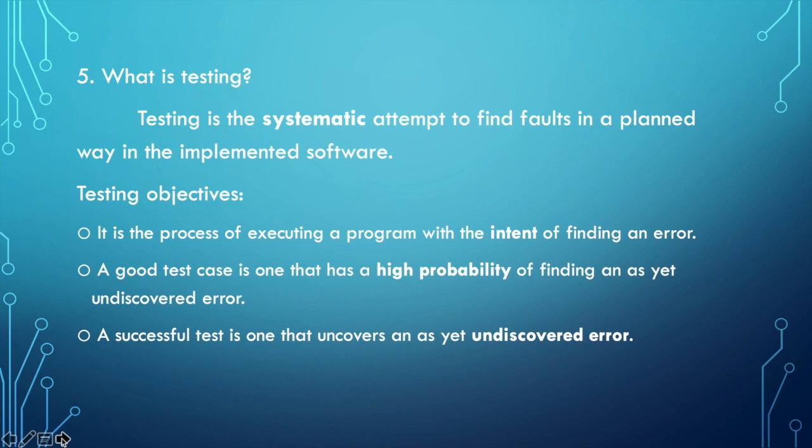And probably in that MCAS, the undiscovered error was that they rely on a reading of only one sensor when there should be a verification of another sensor to verify the reading of one sensor. So two sensors cannot be wrong at the same time, right? Because if the two give different readings, then the software should not be activated.